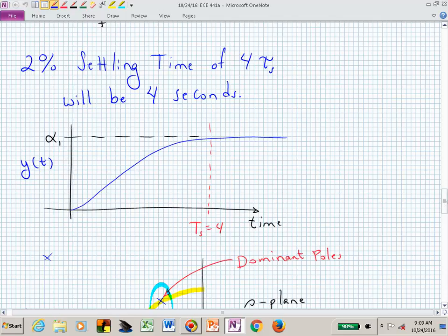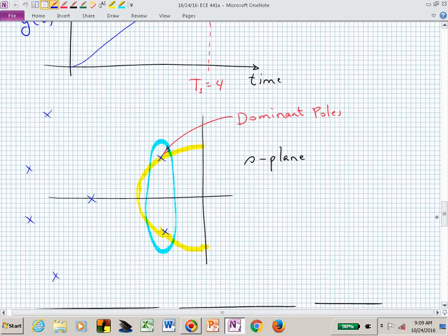And in general, in this class, we have agreed if we have this constellation of poles, in this case I'm just concentrating on the open loop poles, they're X's, the dominant ones are the ones that are closest to the origin. That's what we're calling the dominant. If they're complex, then those 2 are the ones that are going to be dominant.